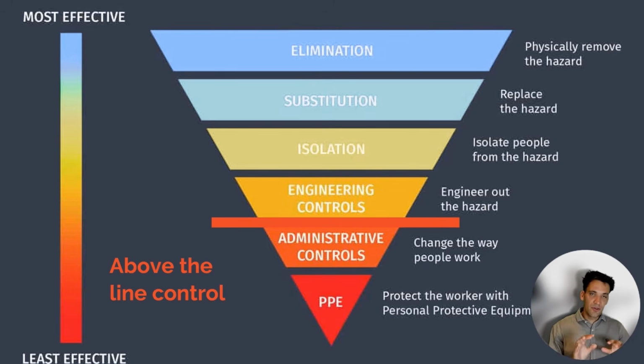Okay, so we can clearly define what is a sufficient level of control based on this hierarchy of controls. For any activity where we're exposed to a hazard, we need to have, as a minimum, an engineering control. We can't have an administrative control and a PPE to eliminate the hazard. So we can't say, in that example of people having to walk along a road to get to the construction site, it's not sufficient to simply say you're not allowed to walk within 2 meters of the road. You have to put in some sort of barricading to isolate or engineer out the hazard. For example, working at heights, if you have an exposed edge, you can't simply tell people you're not allowed to walk up to the edge. You need to put in place some sort of scaffolding that eliminates and or engineers out the hazard.